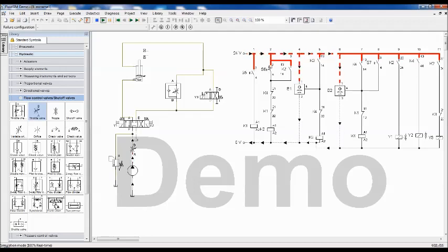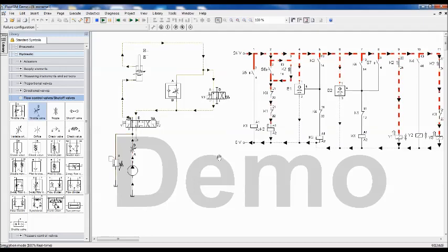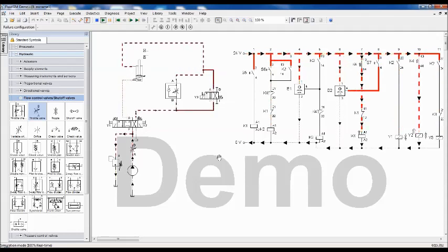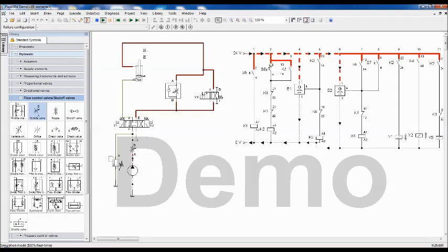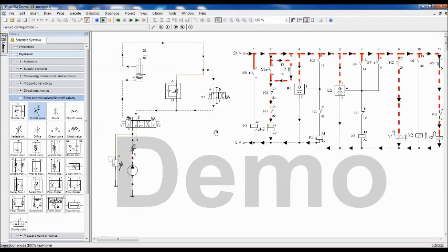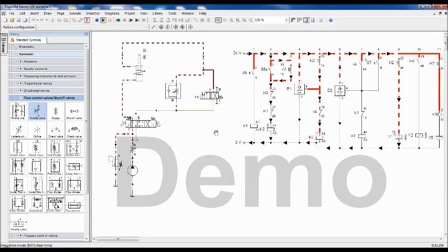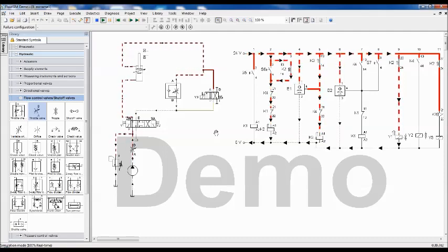If you operate S6, still it is not detecting, reducing the speed. So now when sensor B1 is on, further speed is, see now it is very slow. It is called feed, or the creep movement, or very slow movement of this cylinder.